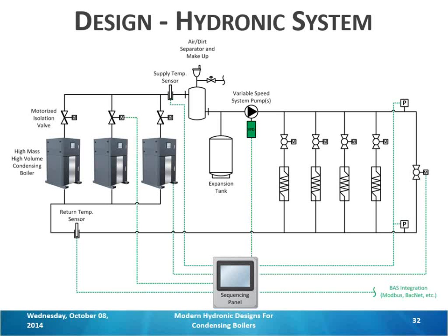If we look at this on design day, we have 3 boilers, and all 3 of them are running, and they're running at 70% input. But we could also do this with 2 boilers at 100% input. But if you remember back, condensing boilers are more efficient at lower firing rates. So if we can operate multiple boilers in parallel instead of 1 boiler at high fire, we're actually more efficient by several points, and we'll save the customer on gas or propane.